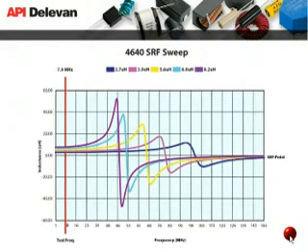The test frequency shown here is down in the flat area where the line is drawn at 7.9 MHz. So the test frequency is found in the linear or flat position of the curve, and not in the severe slope of the curve. Optimum inductor performance is achieved in the linear portion of the curve. The curves show inductance increasing dramatically and then falling to zero. Finally, inductance goes down dramatically at the SRF point.